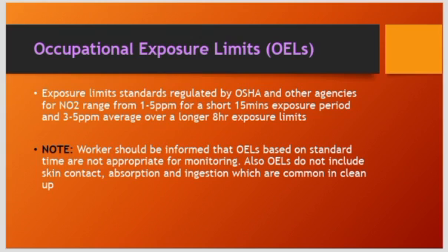Understand? And they say workers should be informed that OELs based on standard time are not appropriate for monitoring. Now, the standard times given above are not applicable to monitoring. You understand? And they also said OELs do not include skin contact, absorption, and ingestion, which are common in cleanup.